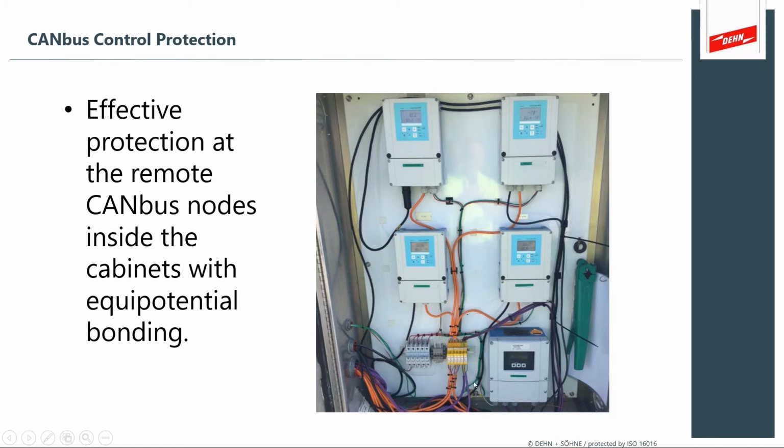We have a central node for bonding down in the lower center of the cabinet, and this provides that single point ground, and this earthing would be connected to your earth electrode system. And what's important is that you have that control of your surge directly at the point of use.